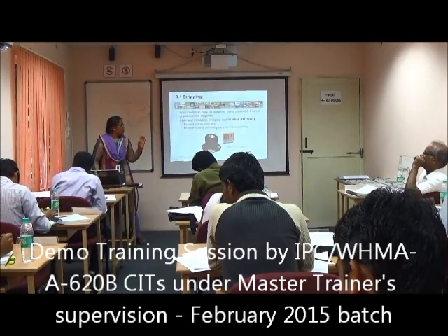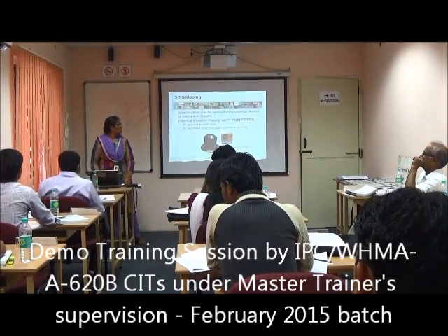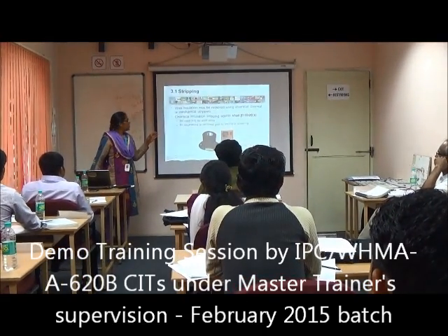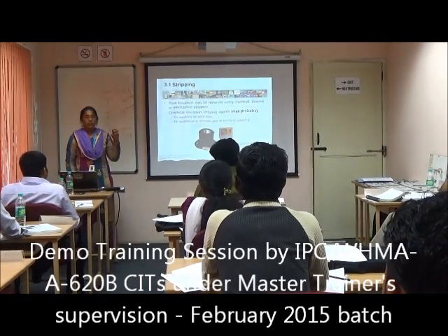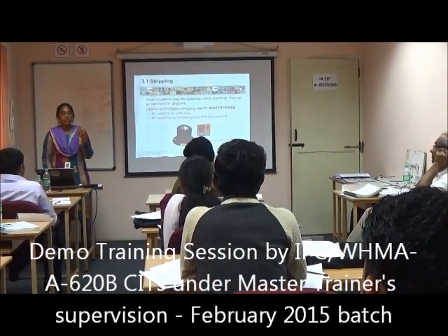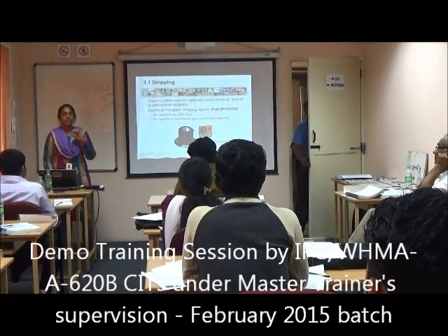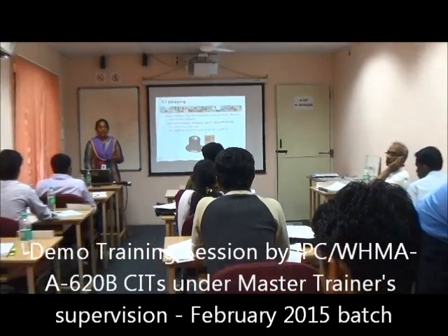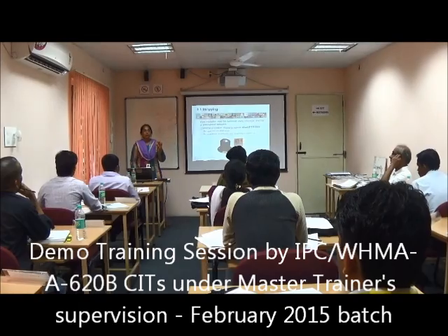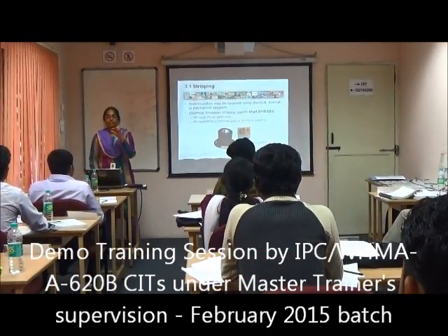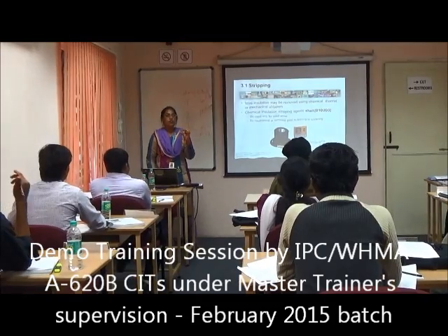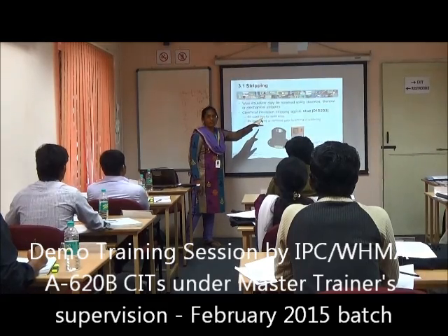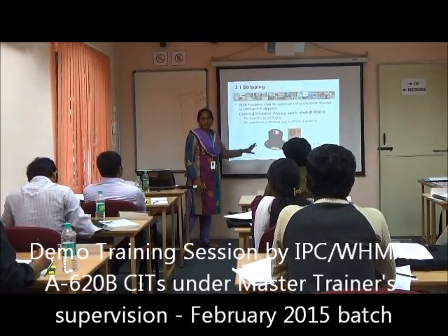In that, if you come across this chemical insulation stripping agent, it is shell. Means when you are using this chemical insulation stripping type, you have to always see that you are dipping a solid wire which has a solid conductor, not strands. Understood? People are able to follow? For example, take a coaxial cable. There, the conductor is solid, not stranded wire. You can't dip stranded wire in the chemical solution. So they are telling it should be used only for solid wires. People are following? Any doubts?